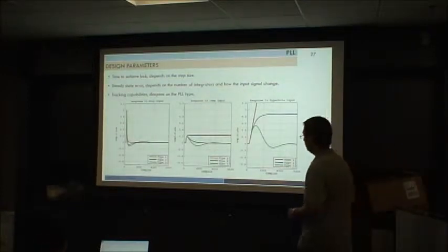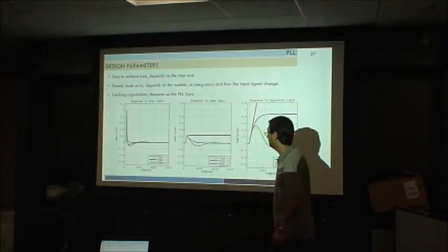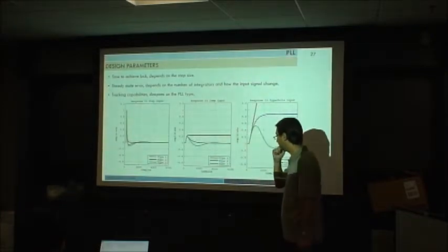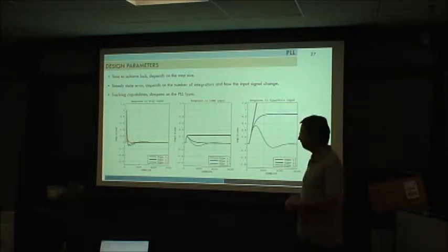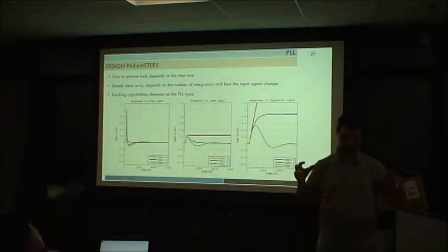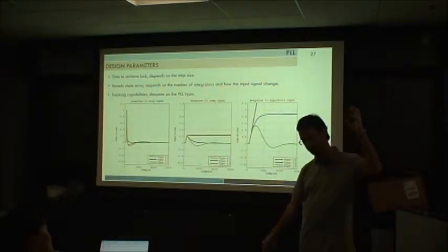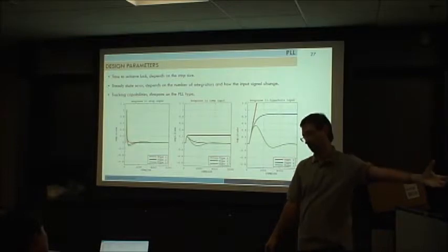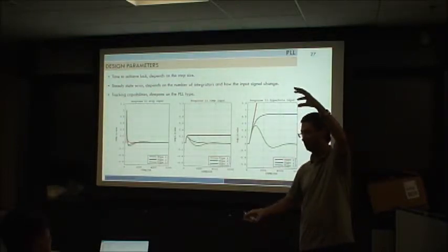So that's why I told you that type 1 cannot follow, because it will have a stationary error there forever. But usually type 2 and type 3 can follow. And finally, this variation is called a hyperbolic variation. That happens related to the Doppler effect between the receivers on Earth and the GPS satellites, because the speed of the satellite is quite big relative to someone moving here.